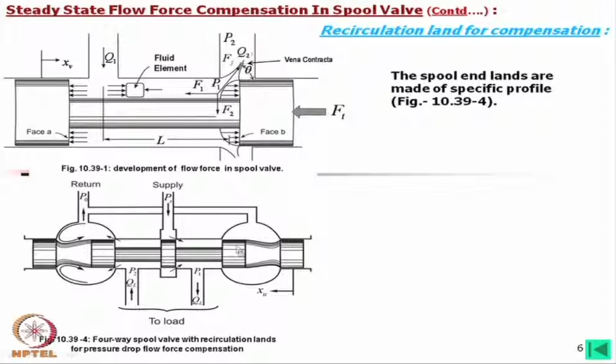Also, the sleeve groove is made like this, but still if you look into this, the orifice is full rectangular, because the orifice area is calculated as stroke length times pi times this diameter. So, this is rectangular, but instead of a rectangular groove, this is somewhat spherical groove inside.